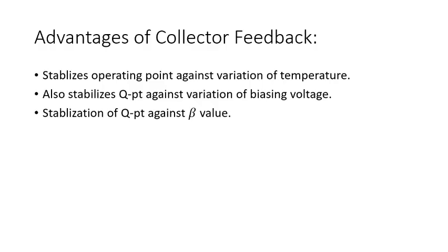Advantages of collector feedback. It stabilizes the operating point against the variation of temperature. It also stabilizes operating point against variation of biasing voltage and also stabilizes operating point against the beta value.